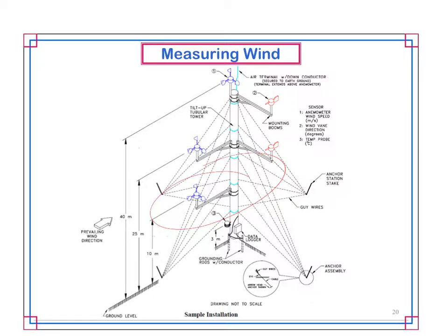It's going to slow the wind down, and it's a solid cylindrical piece of pipe essentially that is tilted up. So you want to be a certain distance away. And you literally use the guy wires to help you start to tilt up the tower. And then you have 3 sets of guys located 120 degrees apart, and then you have multiple locations.